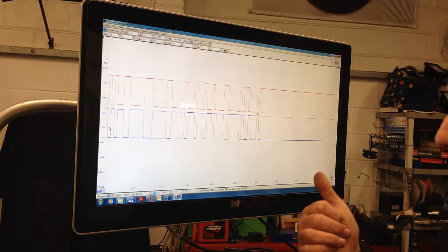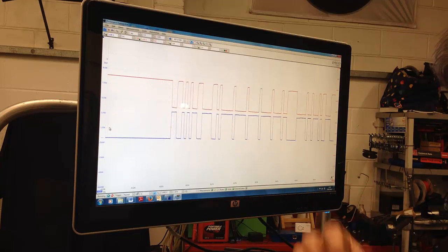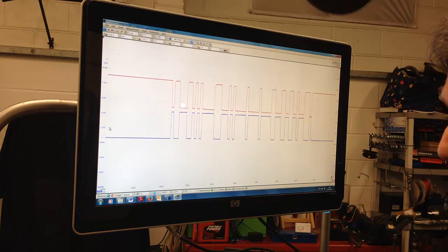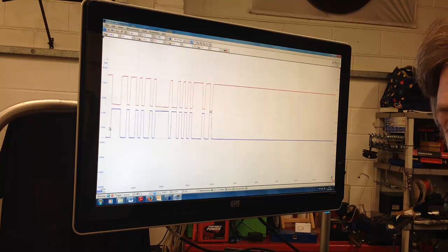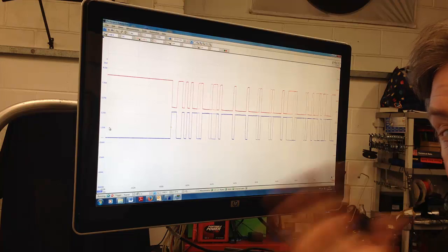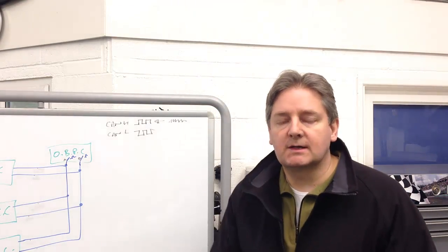So it looks like we could have a fix on this car. The CAN network signal's now cool. It looks like it should. The signal functions on the car, wipers, lights are great. All that remains now, we'll plug into the scan tool, have a quick look for fault codes and data, clear that one up, and then we can count this as a fix. So there we have our fix. New body control module sorted our A4.